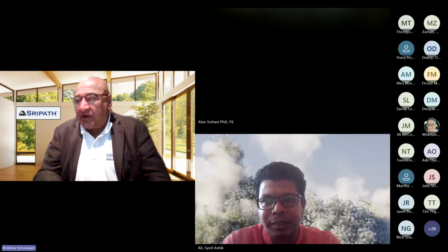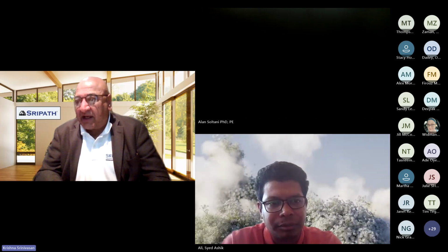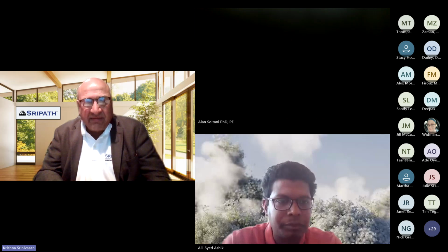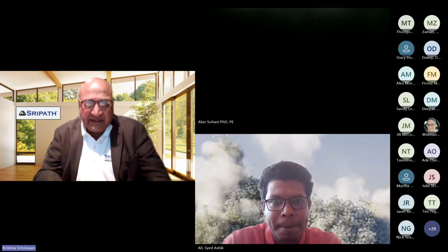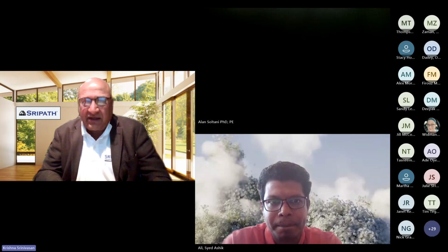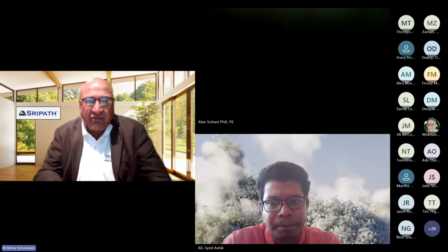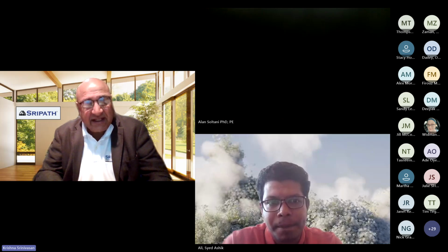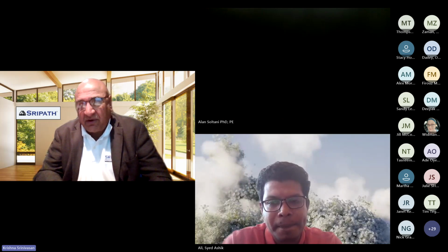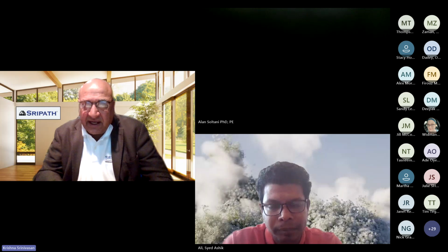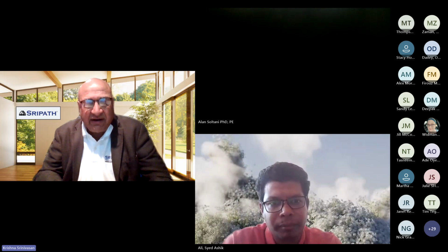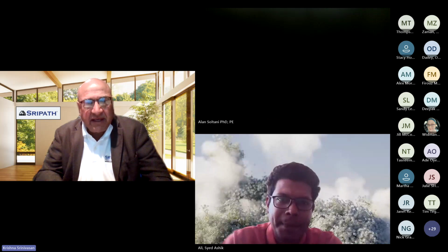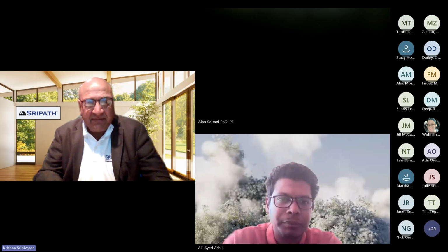Yeah, this is again a question that I think is somewhat academic in nature, and here's why. As I mentioned before, you're adding 1 kilogram of rejuvenator to a ton of mix. It is hardly possible that it will alter the SARA fractions to the point where it's even meaningful or noticeable. Having said that, what really matters is performance. And I think that's where more DOTs are gravitating towards, which is: what is the performance of my mix? How is it behaving on a roadway? Does it last a long time?